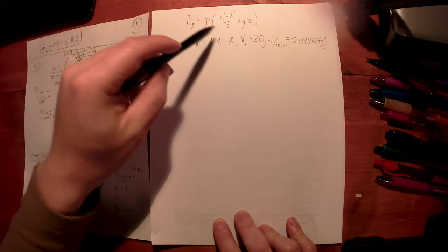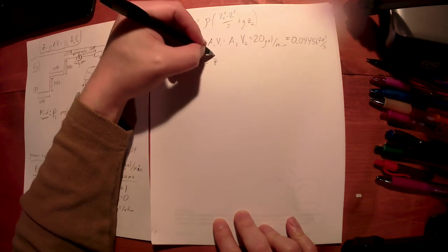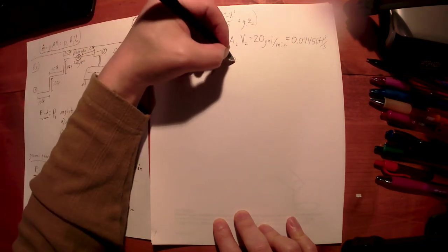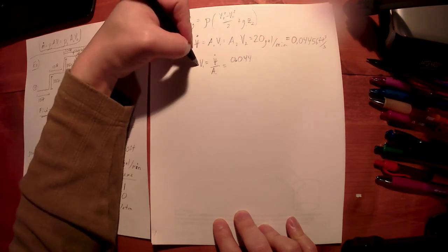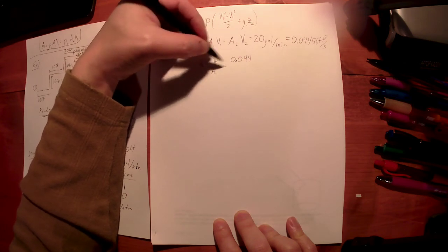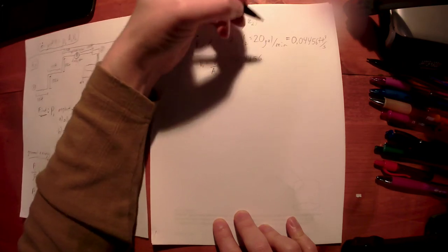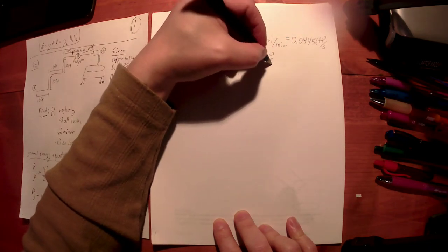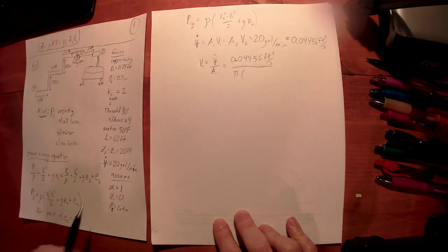So what do we need? Well, we need these V's. Alright, well let's find V1 first. V1 is going to be V dot divided by A1, so that's going to be this 0.044. Now why would I convert that? Well, I want V to be in feet per second. So I'm going to have area in feet squared, and if I've got this in cubic feet per second, then this ends up being feet per second. So 0.04456 cubic feet per second divided by,